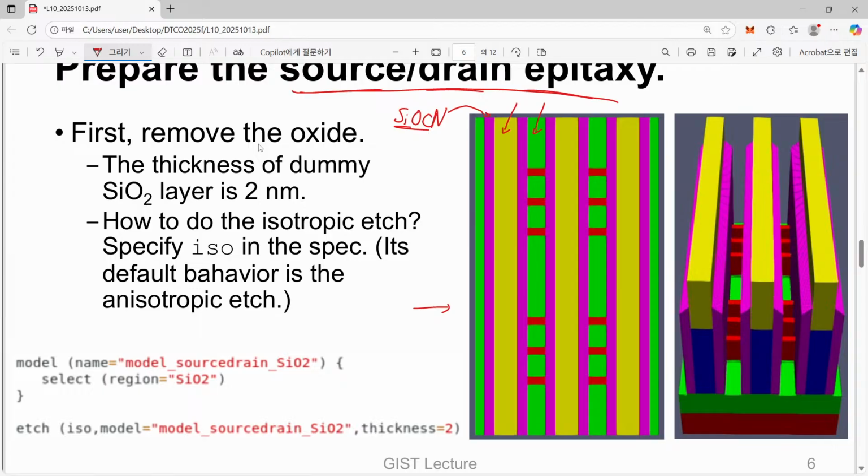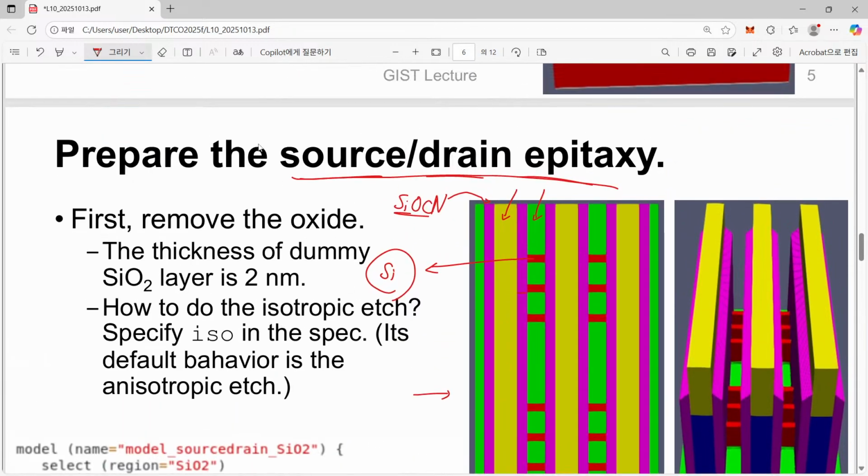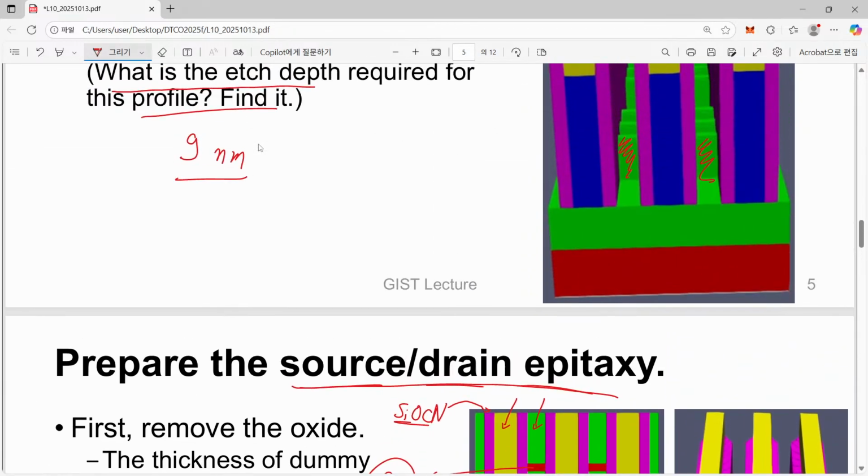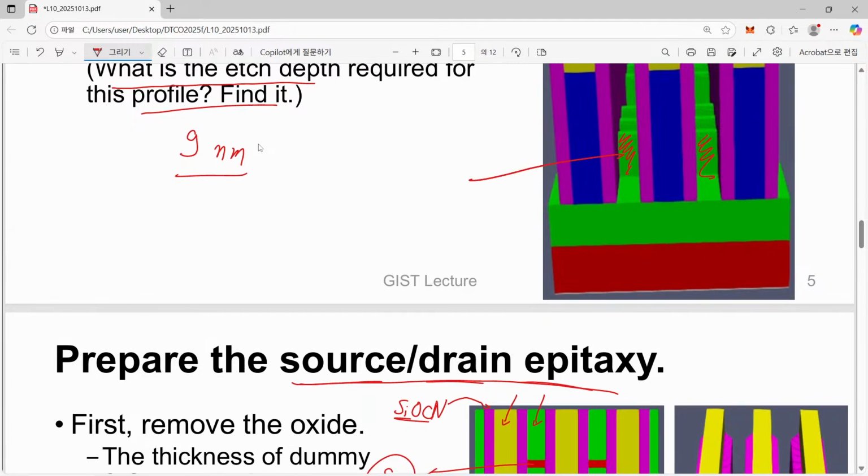And here we have just a lead region, and in my current example, this lead region corresponds to silicon. Then just doing silicon oxynitride etching, we still have a dummy gate. This green one is a dummy dielectric, corresponding to silicon dioxide.